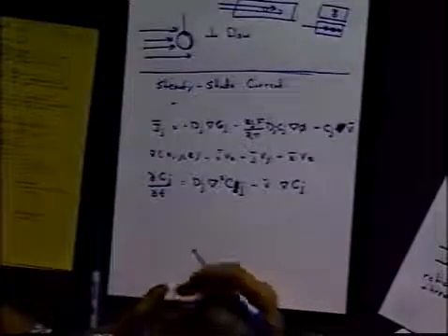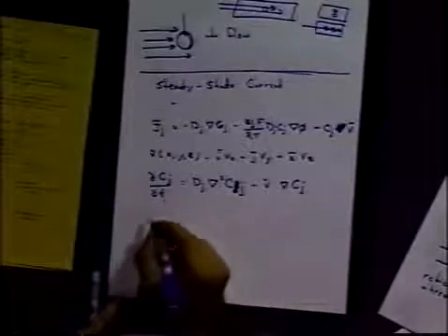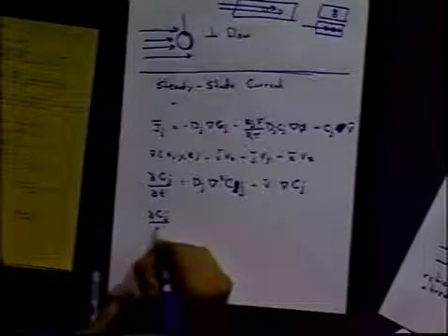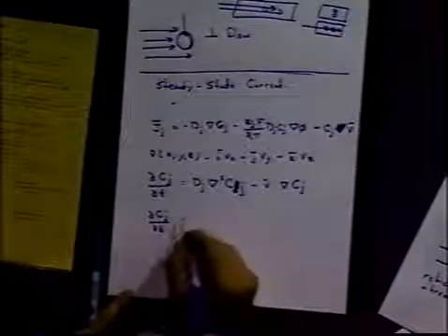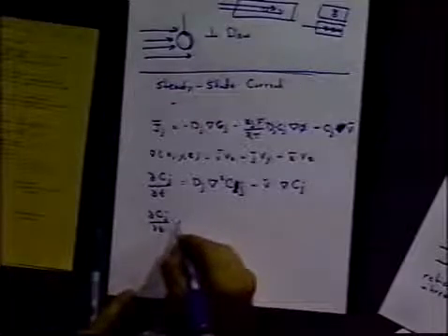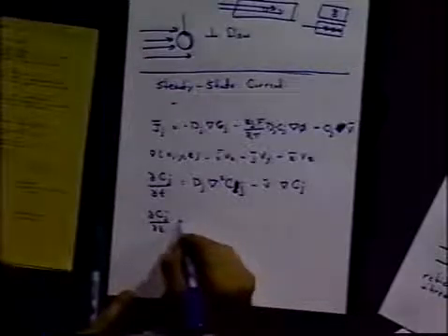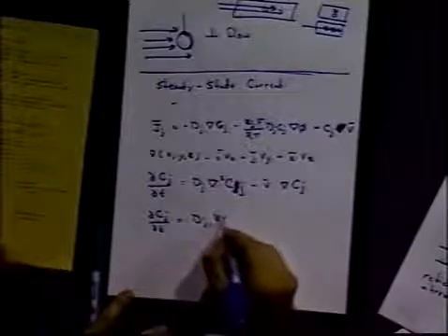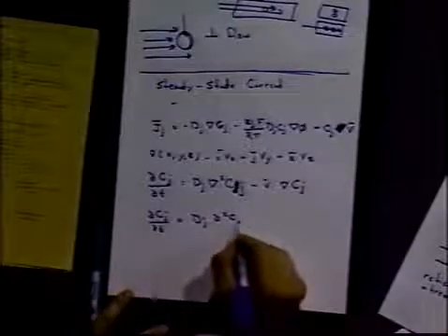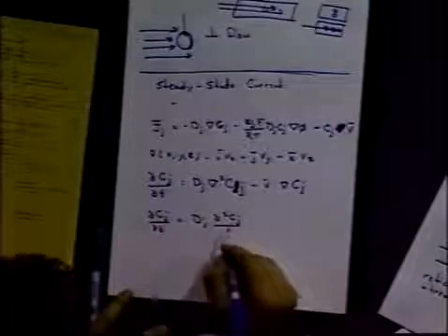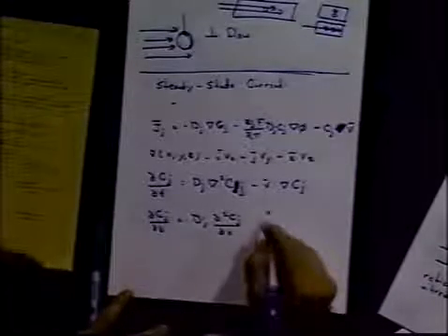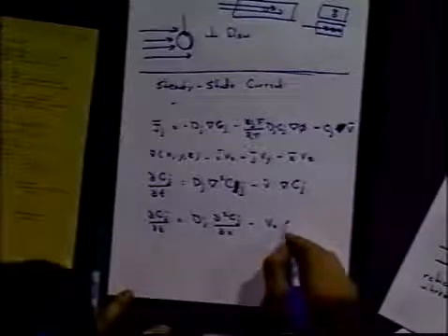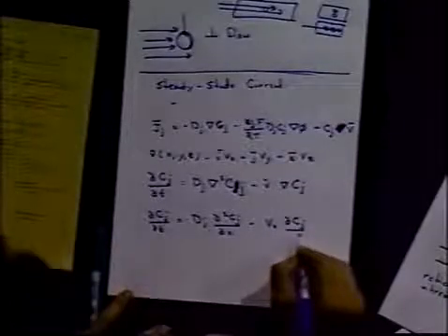So we set up the experiment so that we only have one-dimensional worries. As always, we use x as that direction. So the change of the concentration of species J as a function of time in one direction is the diffusion term, the second derivative of the concentration with respect to x, minus the velocity in the x direction times the gradient of species J.